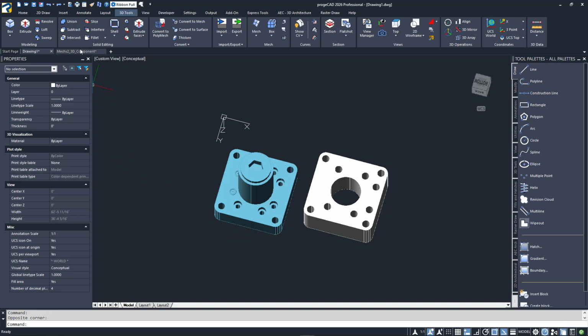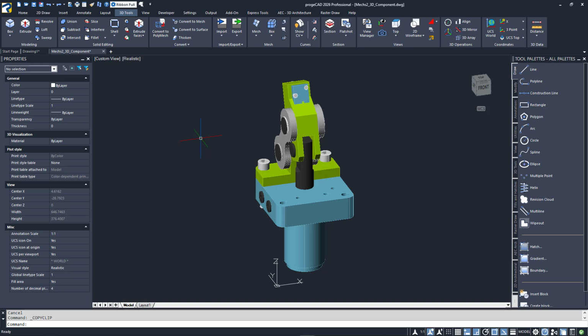I'll go back to our full assembly drawing now and show you some methods to better your work in 3D model space. I've talked about layout viewports, which you use to view your model in paper space, which is then scaled and plotted. Model space supports viewports as well, but they're used differently and have some different properties.